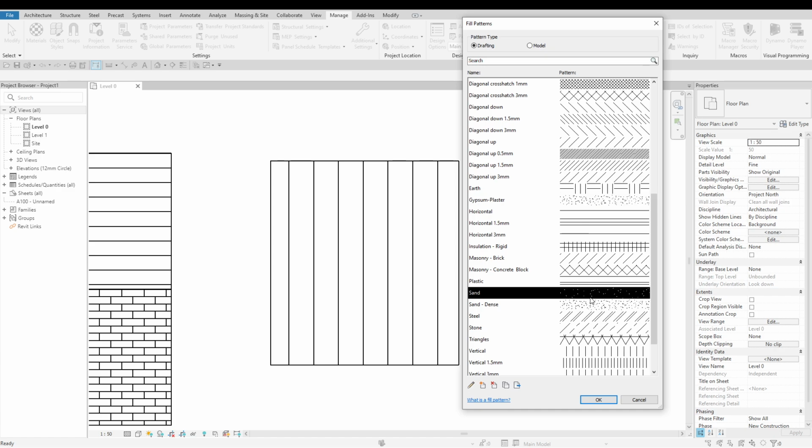You can create the desired pattern geometry within AutoCAD and then utilize external conversion tools to generate PAT file, which can be imported into Revit. Alternatively, third-party applications and plugins designed for pattern generation can be used to streamline the creation and export process. In addition, a wide range of pre-configured pattern files is available from reputable online sources, offering ready-to-use solutions for various design needs. These approaches help bridge the current gap in native software capabilities and provide practical alternatives for professionals who require custom fill patterns within their BIM workflows.